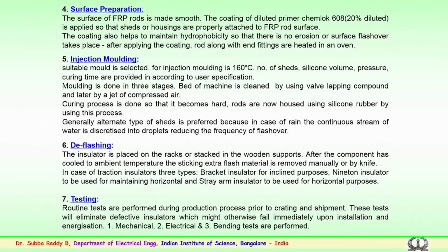So, on testing: routine tests. After the insulators are ready, they have to undergo routine tests in the factory, performed during production before the crating and shipment is done. These tests, mechanical, electrical or thermo-mechanical, will eliminate defective insulators which might otherwise fail immediately upon installation and energization.